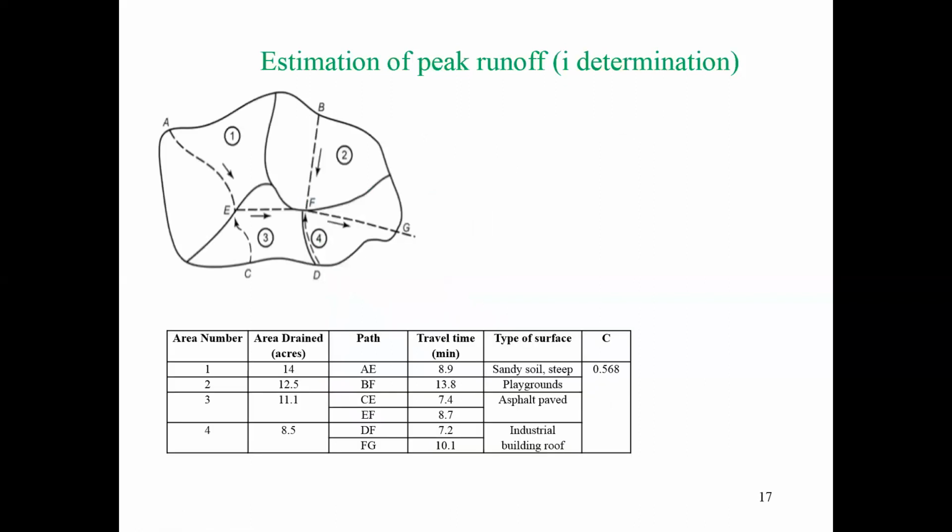As we just saw, we need to know the time of concentration, and we already know time of concentration is the maximum time water will take to come to the outlet from the farthest point. Now we have 1, 2, 3, 4 areas, and for each sub area we have some travel time, you can see here.